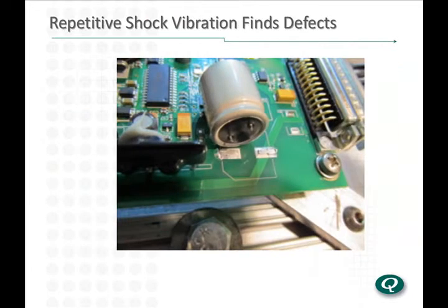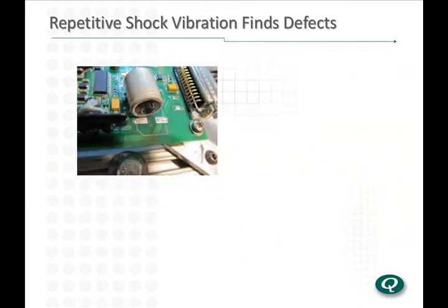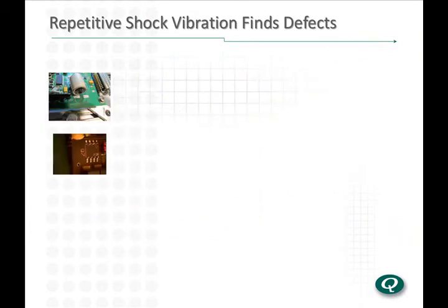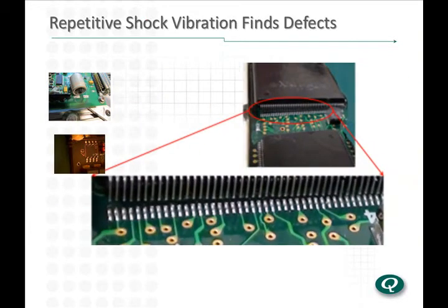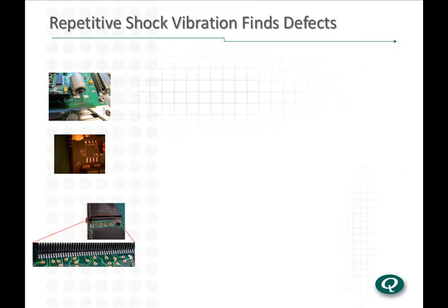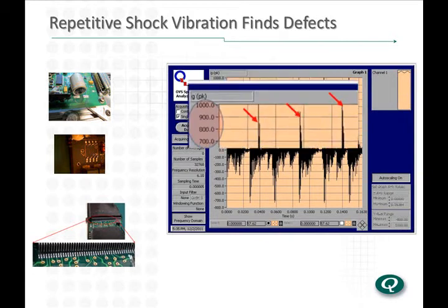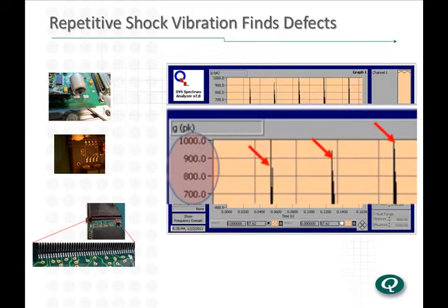Mechanically weak or defective components quickly fail because the shocks produce excitation in all three axes simultaneously across a wide frequency range. The real-time acceleration response from the product clearly shows high acceleration stresses, with peak accelerations that are much higher than are possible using an ED shaker.